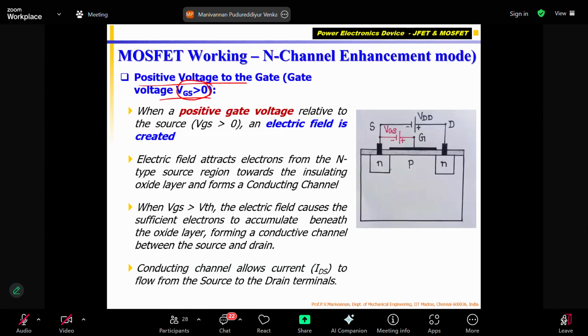To make this MOSFET work, apart from supplying VDS, for example 100 volts, with drain connected to positive and negative connected to source, fantastic, drain to source is forward bias. Now I am adding one more power supply, which is called VGS, which is called a control signal. The negative of the second power supply is connected to source. Please note that this can be a sensor, a control signal coming from a sensor.